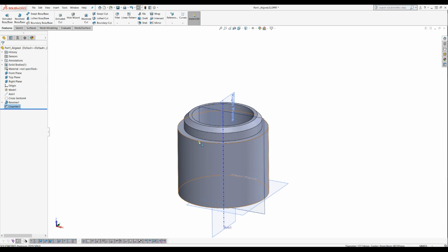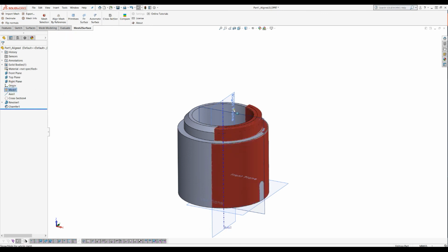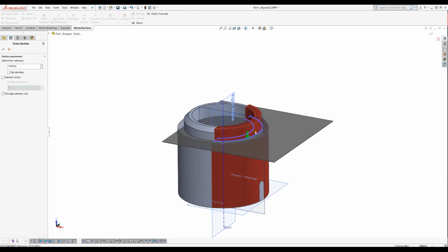When you have a body like this one, you can always pre-select a flat surface that you can just take, and if you want to have the cross sections enabled, you must have the visual mesh that these sections will go through. And now I can just pick, and we will create a section here.